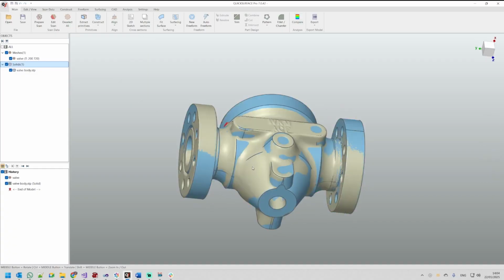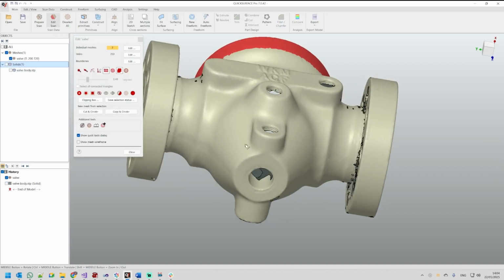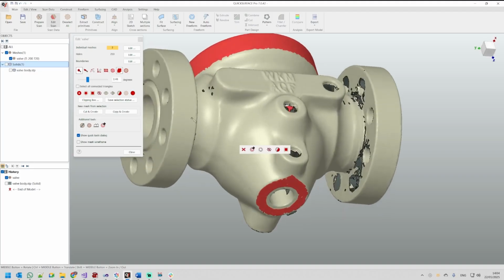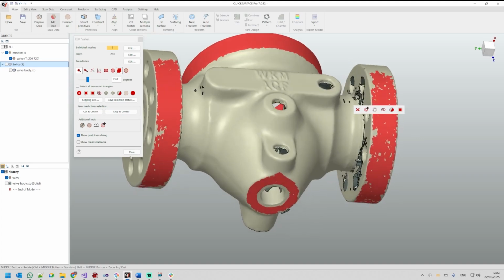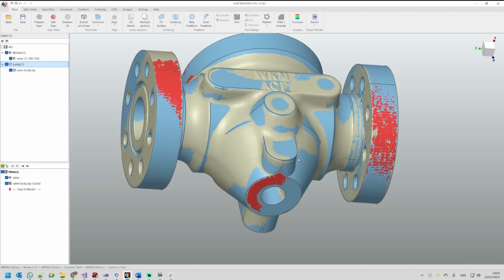You can play even more. For example, I can use my magic wand here. I can select the top. I can add probably these cylinders here to be used in the alignment, and then I can do the alignment again. So you can do this several times.